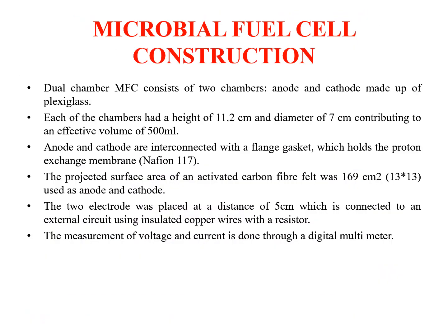Microbial fuel cell construction. The dual-chambered microbial fuel cell consists of two chambers, anode and cathode, which are made of plexiglass. Each chamber had a height of 11.2 cm and a diameter of 7 cm. Anode and cathode are interconnected with a flange gasket which holds the proton exchange membrane, Nafion 117.